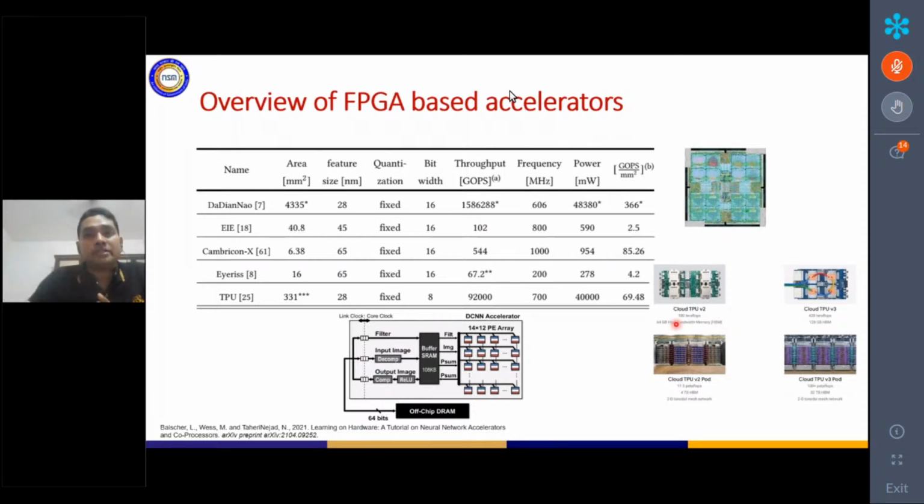All these computation engines that you can see here are essentially arrays of processing elements, called systolic array-based engines. These are just arrays of multiply and accumulate engines, and to feed the huge number of processing engines, you can see 12 cross 14 multiplication engines being employed in one. This is the first version of the TPU we are talking about.